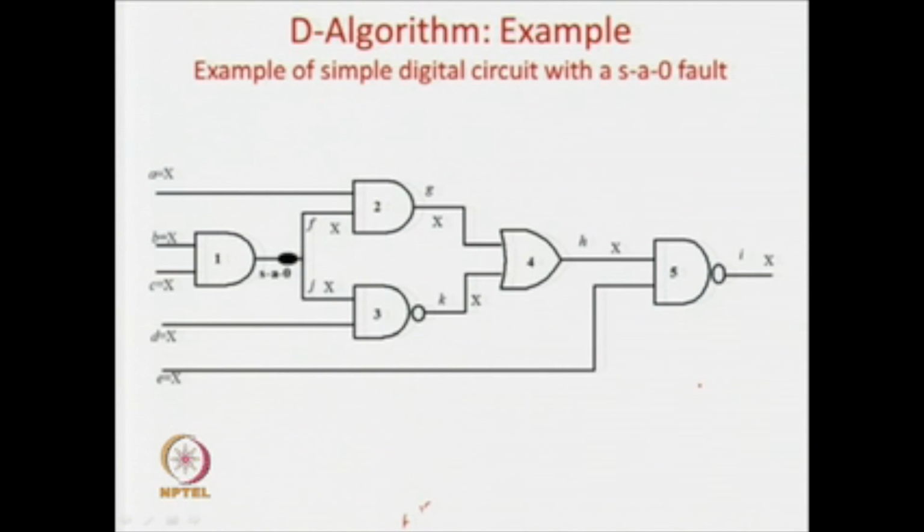But if you could make an intelligent D algorithm, which we will see very briefly, that is PODEM and FAN and henceforth, they intelligently do the backtracking. If there is some intelligent search in the tree, then the D algorithm will not be that complex. But in the general sense, you keep on trying out the options one after another, and that is the killing point of this algorithm. It becomes very complex because you do not have a guided direction of search. But in the advanced algorithms, guided directions of search are slowly coming into the picture.